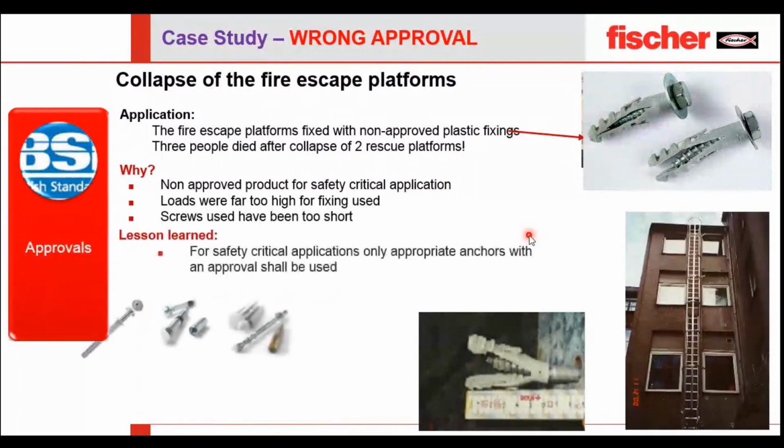So the lesson learned is: if you are not using a proper approved angle, because it's a fire escape route and you need a fire-approved angle for this. If a fire is catching, people need to escape from this place, and if the angle is not approved for fire, for sure it will not withstand, and this application of the system will collapse altogether.